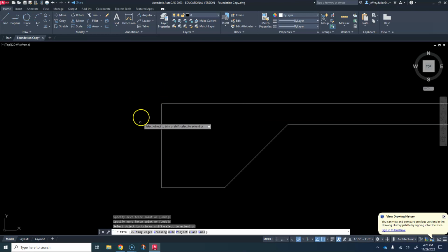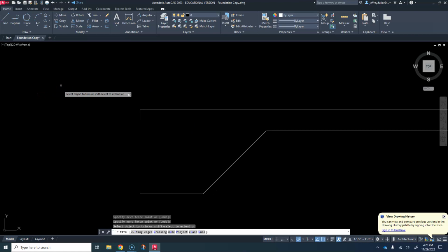Next I'm going to focus on this section and I'm going to draw the brick ledge. Brick ledges come in various lengths and types. Depending on the type of block or brick you're using, you'll have different ways of doing the brick ledge. I'm going to do one. Now I have to add up the thicknesses of my material, because in this brick ledge, it's going to be right here, like a corner cutout. I've got to fit my bricks, I've got to fit my airspace, and I've got to fit my sheathing down in there. So that's 3 items.